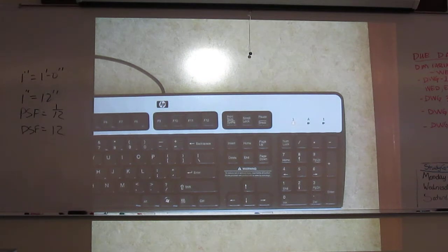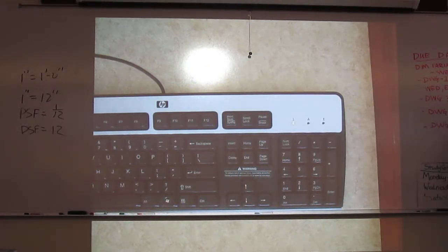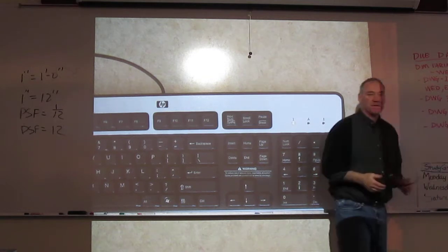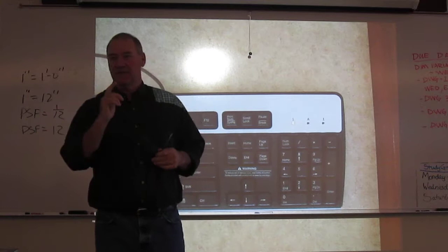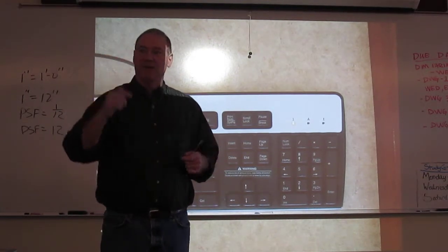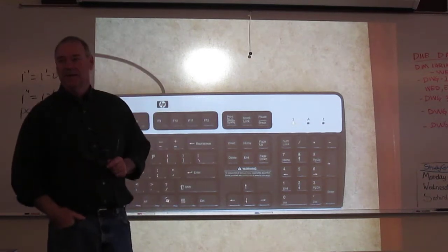You'll need the fractions, because we have fractions in your titles, since we're doing multiple scales. So over here under your scale, you've got the note, right? And then underneath each title, we've got 1/8 inch with the architectural scales. When you've got this guy right here, you're going to do like an 11 7/8. So this will stack those fractions for you automatically. Just do 11 and then hit your 7/8 key and it will place it. And it does it to AIA standards.